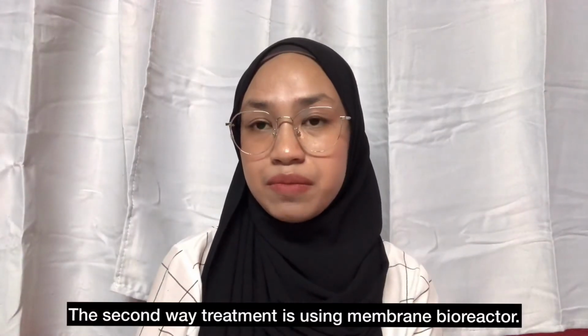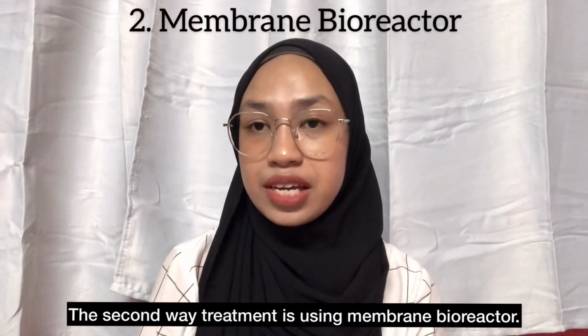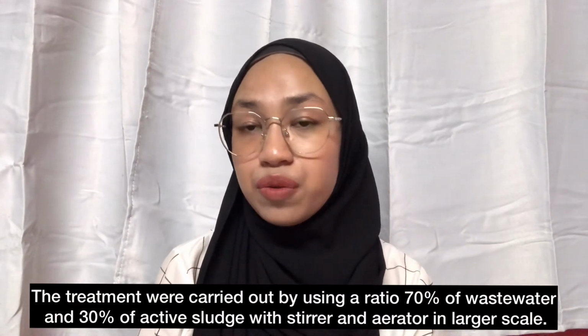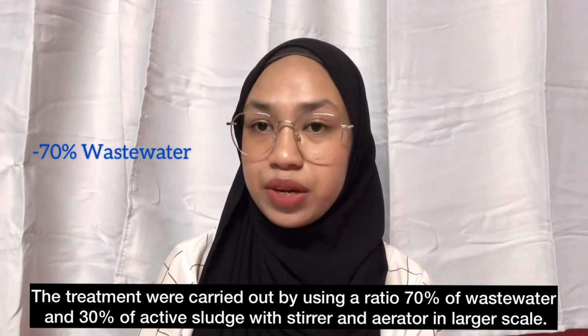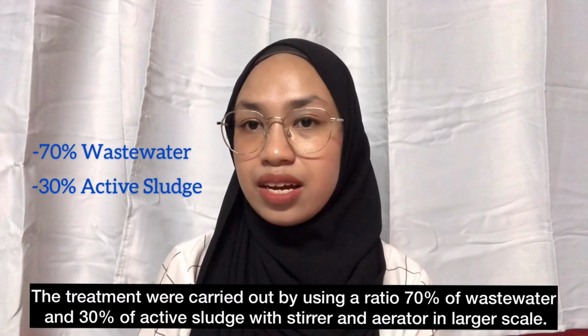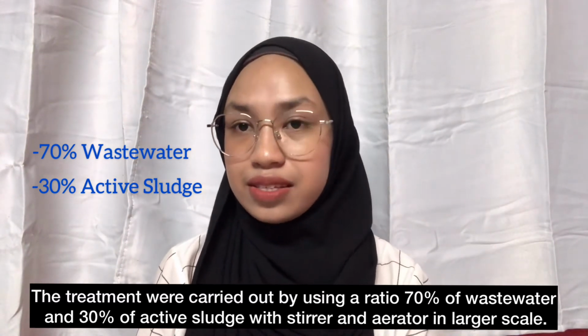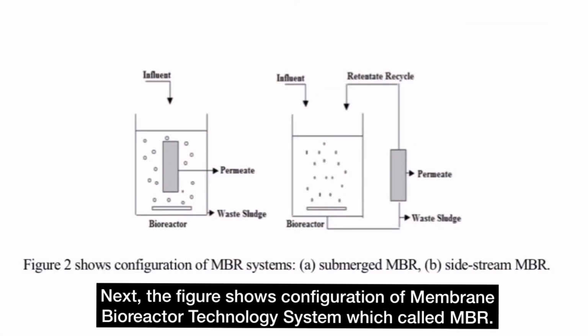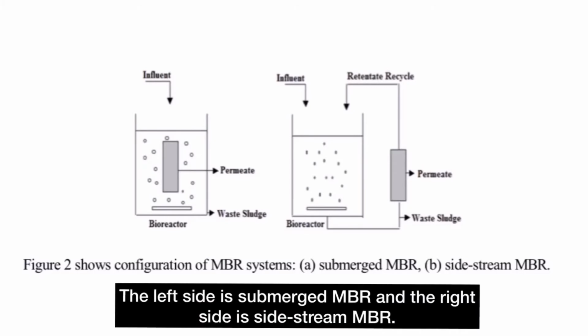The second treatment is using a membrane bioreactor. The treatment will be carried out by using a ratio of 70% wastewater and 30% active sludge with a stirrer and aerator on a large scale. Next, the figure shows the configuration of the membrane bioreactor technology system, which is called MBR. The left side is submerged MBR and the right side is side stream MBR.